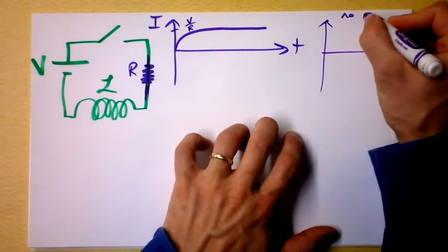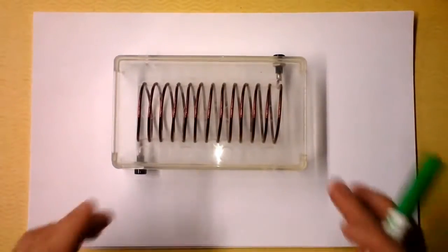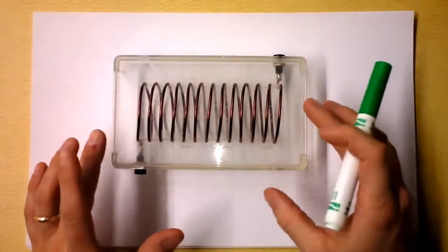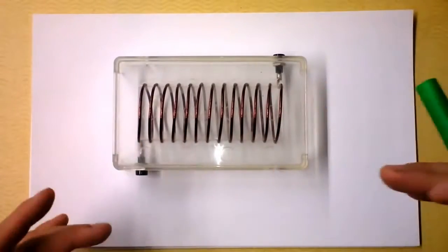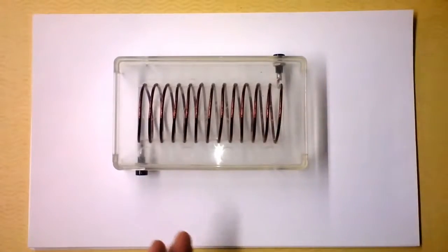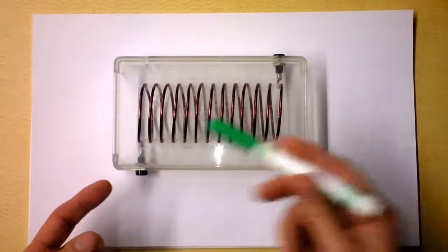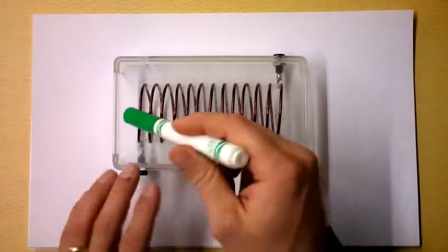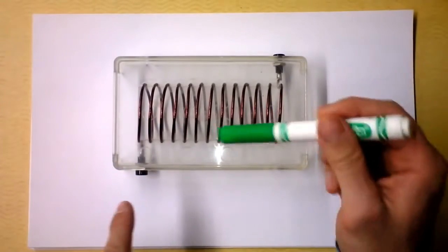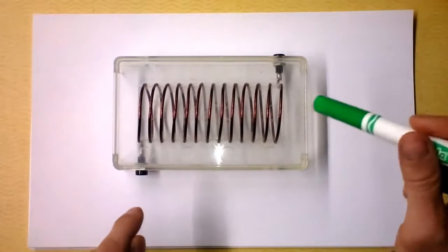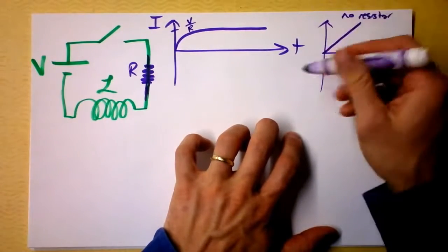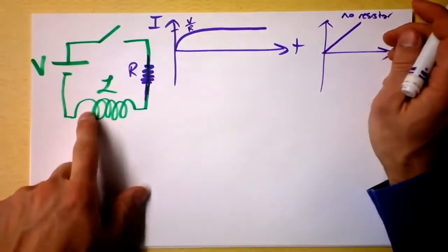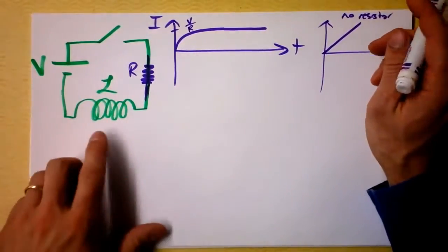You know that if I hook this inductor right here up to a battery, it will behave initially as a bad battery. It doesn't want to have any current in it, and so it rejects the current coming in and pushes it back the other way, because as the field in it changes, the inductor itself induces a voltage in the other direction that tries to not let the current through. No resistor, we would just go like that, and we could put more and more current into this sucker, and that's how you might make an electromagnet, for instance.